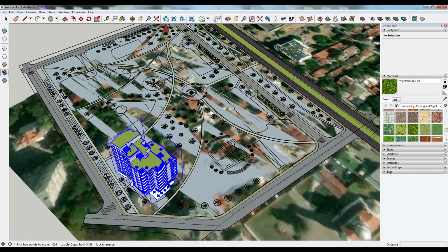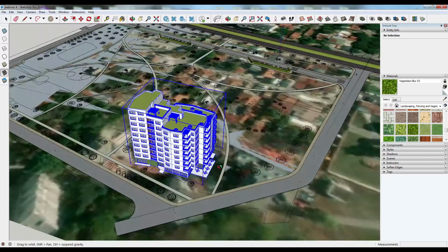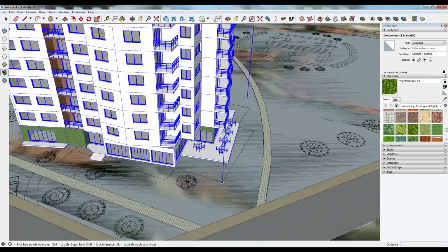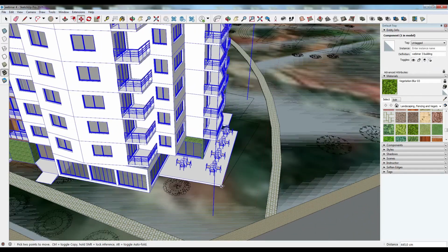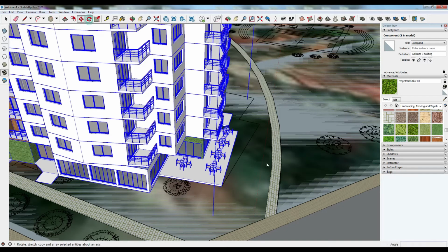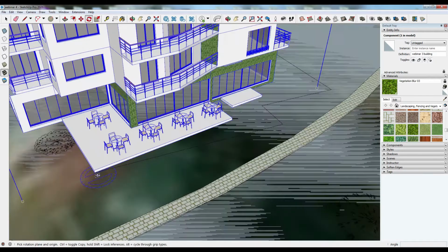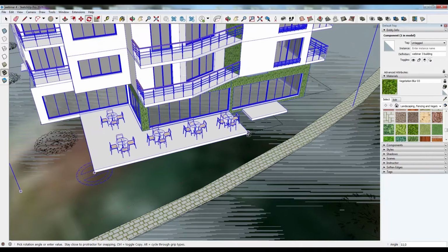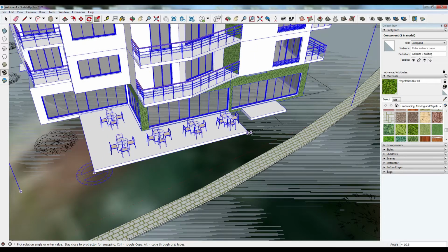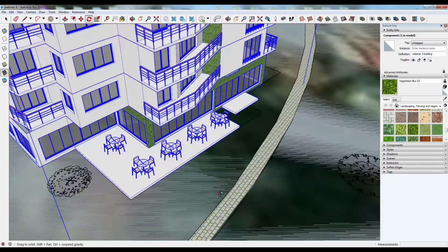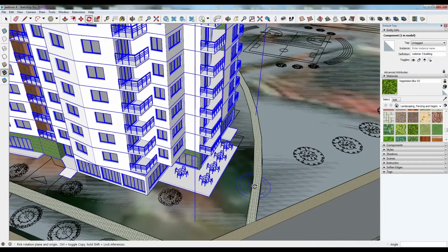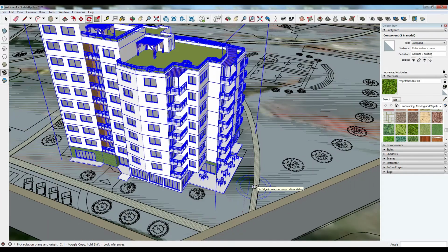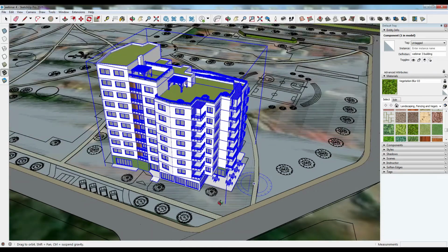It takes a couple of seconds to load, and with the Move tool I place it and align it to a point. With the Rotate tool I first click on the line of the model and then click on the line from the CAD file below. This is how it is all aligned.